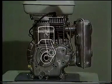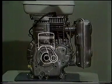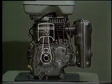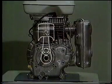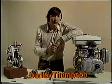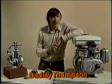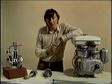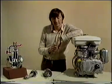I'm going to estimate the force which acts on the piston at top dead centre. This is the point in the engine cycle when the acceleration of the piston is greatest. You should by now be pretty familiar with the line diagram of a slider crank mechanism. Now we're going to look at the actual components which make up that mechanism in the engine.